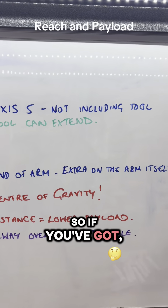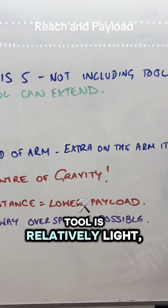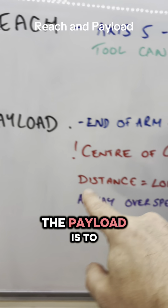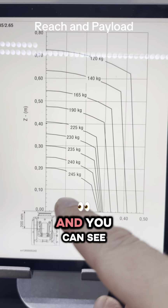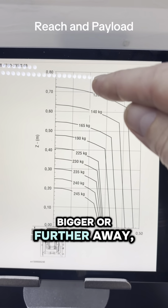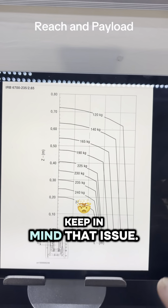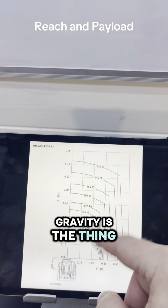So if you've got an application which needs a really big reach, what you can potentially do, as long as the tool is relatively light, is extend the effective work envelope using the tool. The payload is to the end of the arm, so that's the quoted payload here, and you can see as the centre of gravity moves away, so as the tool gets bigger or further away, then the payload decreases. So if you do that trick extending the reach using the tool, then you have to keep in mind that issue. But the centre of gravity is the thing which you need to watch.